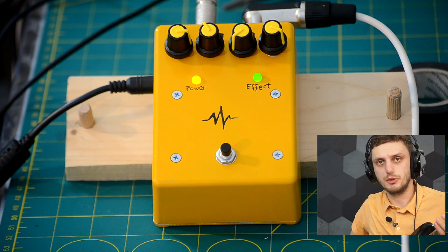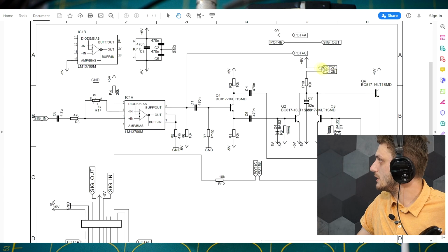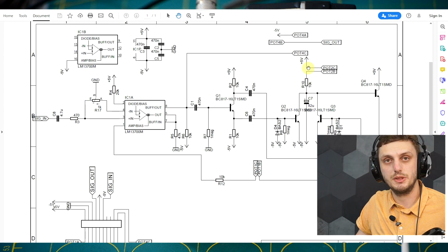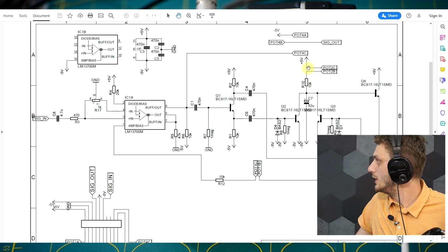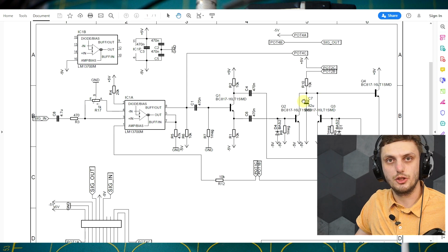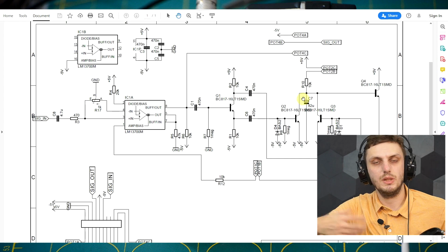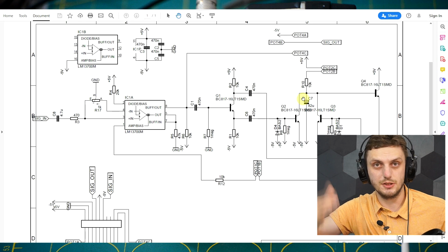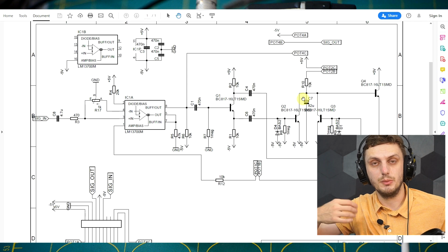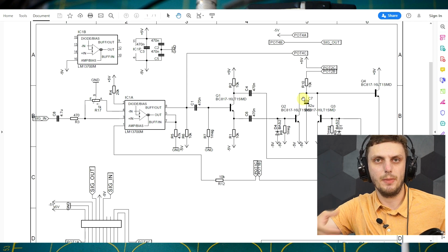Now there's one more potentiometer that I'm using, and this is connected in between my positive supply and my capacitor. The lower the value is here, the faster the capacitor can recharge, whereas if it's higher, then it will charge up slower. Basically this is setting how fast the gain can increase. The gain can decrease very fast because of the transistors. They're directly short-circuiting the capacitors to ground, but to charge the capacitor back up, it will take a bit of time.